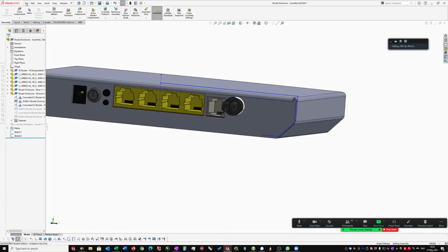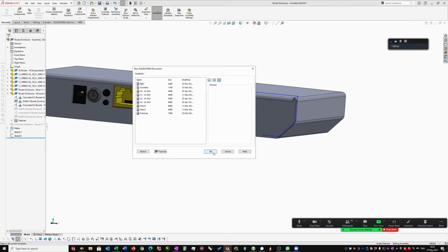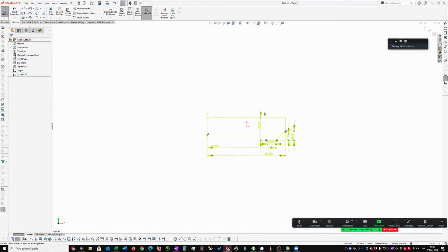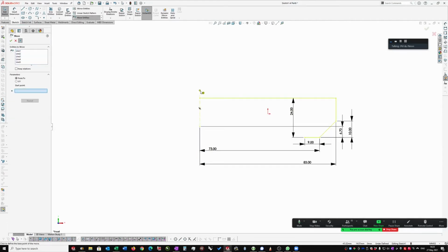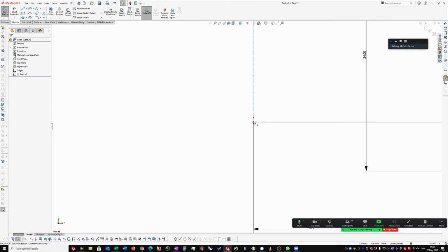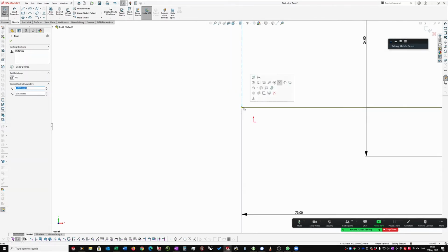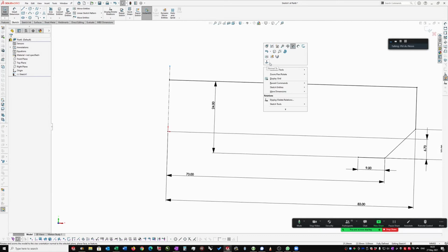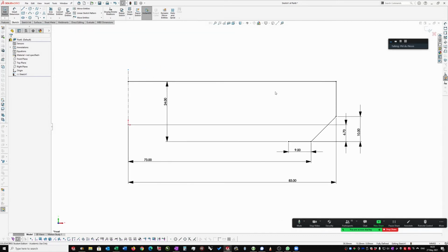Right, so I'd actually probably go and change the shape of that thing so it doesn't do what it's doing here. We'll go to File, New. Front plane and Control V, and so it brings my sketch in. I just need to move it from that point to here. Here you have to be a little bit careful. If it doesn't want to connect straight away, just click on the end of it, click on the origin, and say make coincident. If you've got a fully defined sketch, it'll all go black for you in any case.